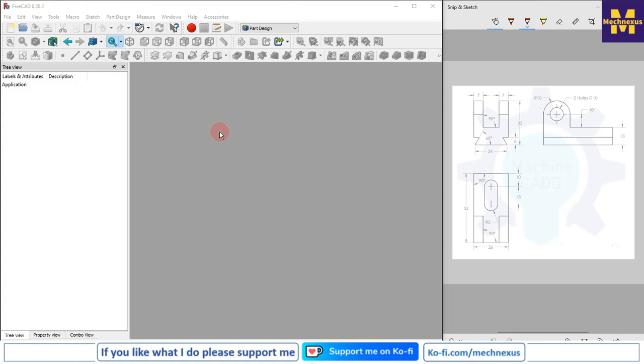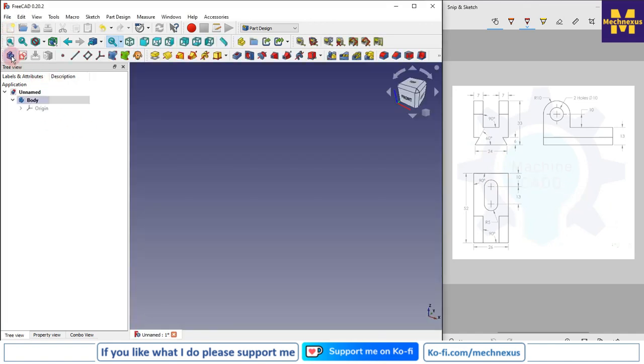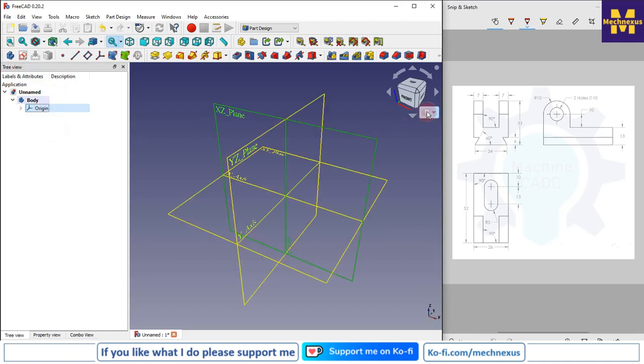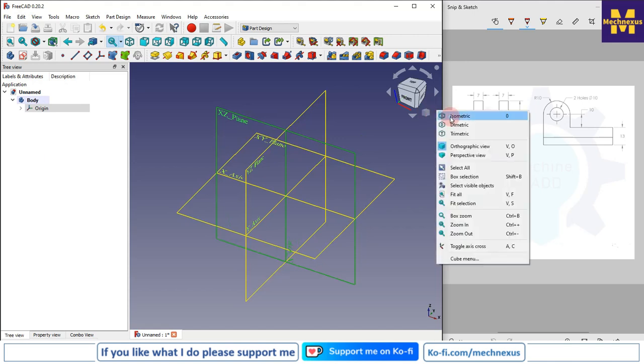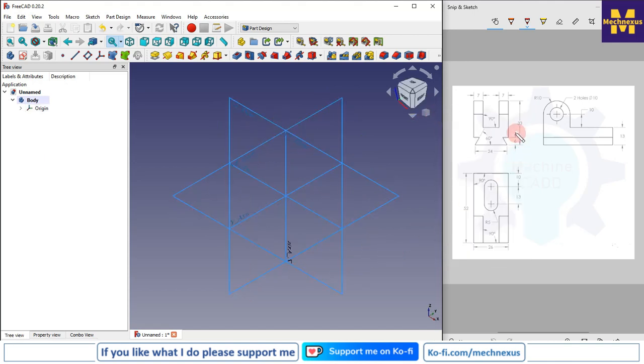Welcome to FreeCAD tutorial, and in this tutorial we will convert this orthographic drawing into the isometric 3D models. So here we have a drawing and it is in a third angle projection. So first we will create a new file and we will create a new body, and I will set my plane to the orthographic, and now we will read our model.